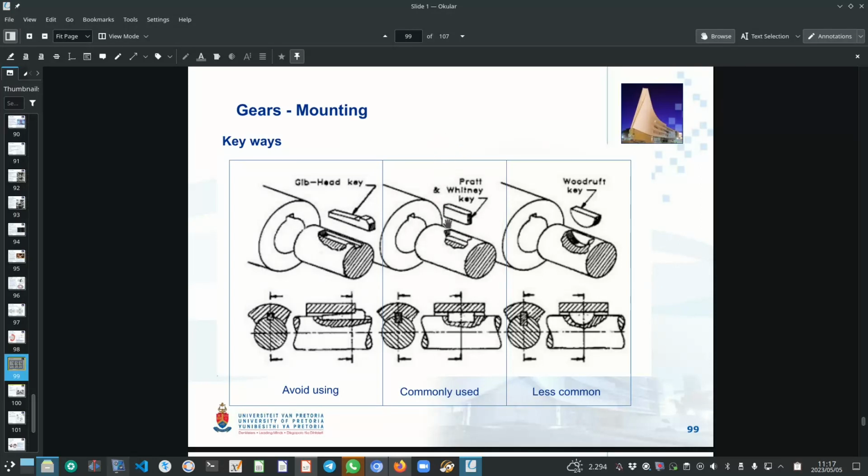It gets pushed into the shaft, and as it rotates, it cuts away the material, it removes the material, and then once it's at the correct depth, this round cutter or end mill cutter is then controlled in the axial direction to the adequate length such that the key can actually then fit into that slot.